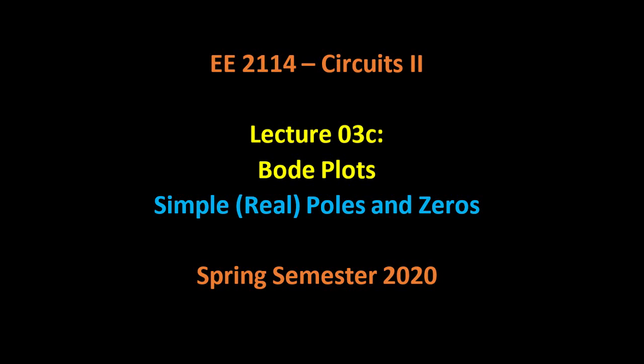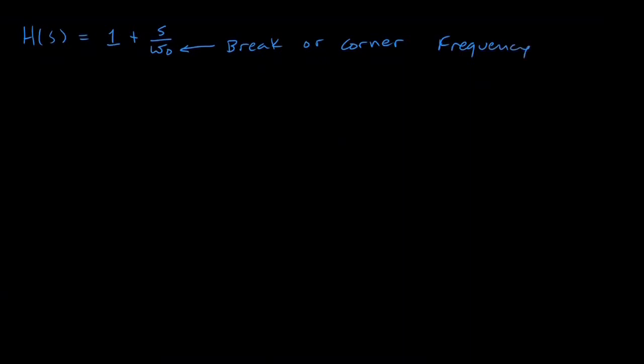This session is going to deal with plotting real poles and zeros, which are also called simple poles and zeros. A simple zero is going to have the form H(s) = 1 + s/ω0. ω0 is a constant, so that's going to be called the break or corner frequency. And you'll see why we call it the break or the corner frequency in just a moment.